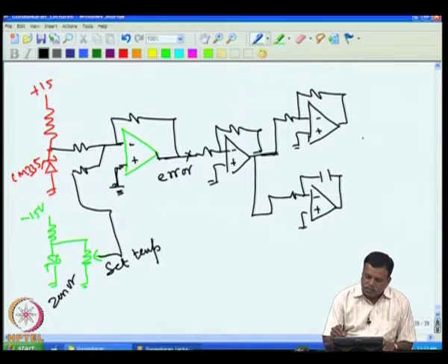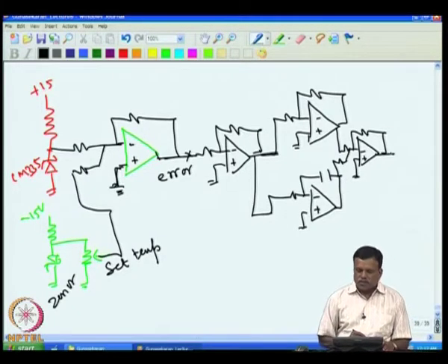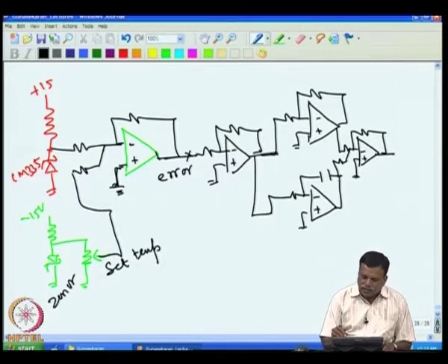Now, what we do is we sum these two voltages. Here I sum it, and this I can add to this. So, essentially you are adding the integral output and the proportional gain. This gives you the gain. So, this is the error voltage. When temperature goes up, this increases, then correspondingly this is amplified and it will be going minus, and that will be inverted and you will get a plus. And then whenever error is there, this slowly charges up the capacitor, and this voltage also will go towards minus, and that will become plus.